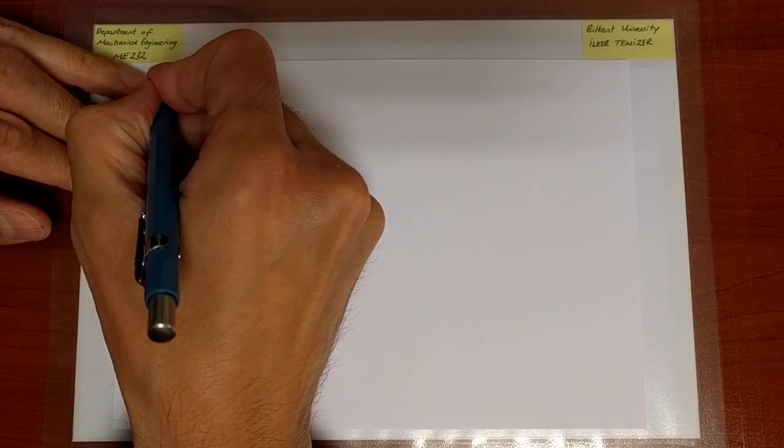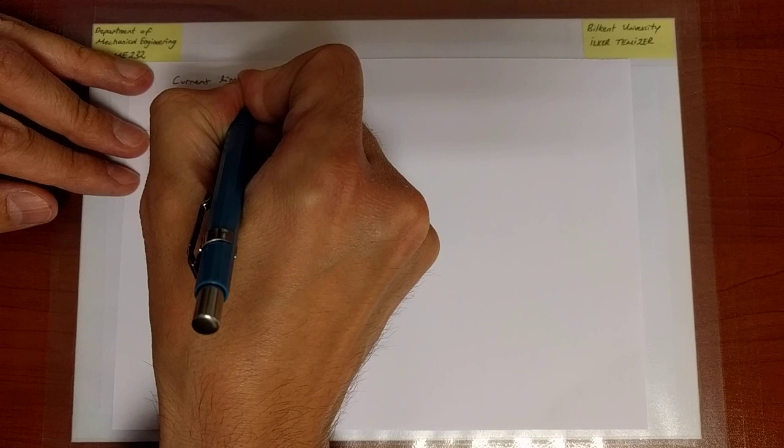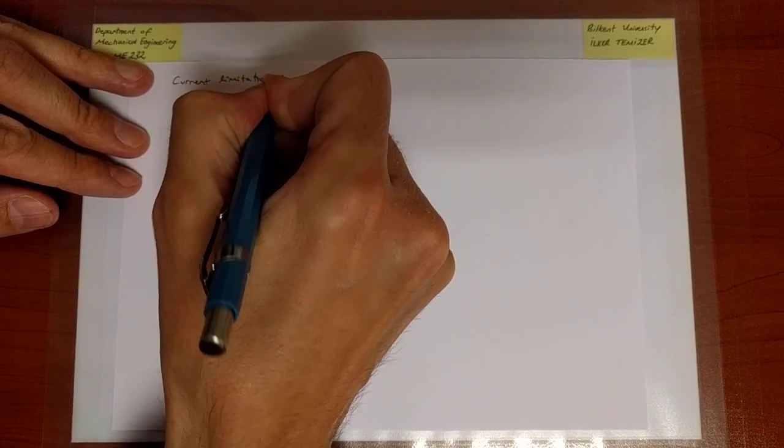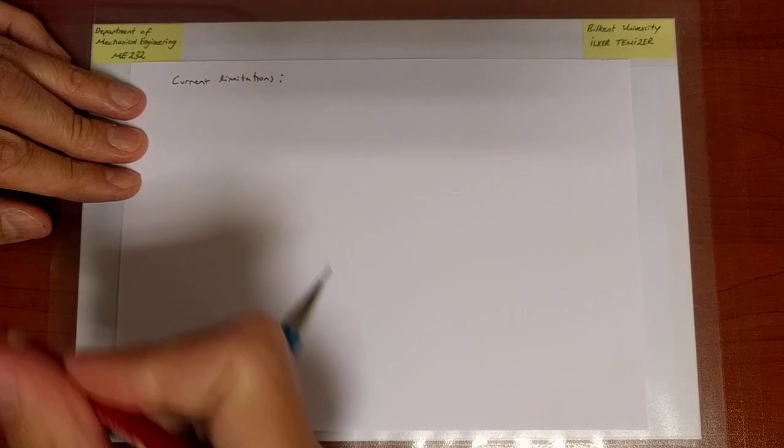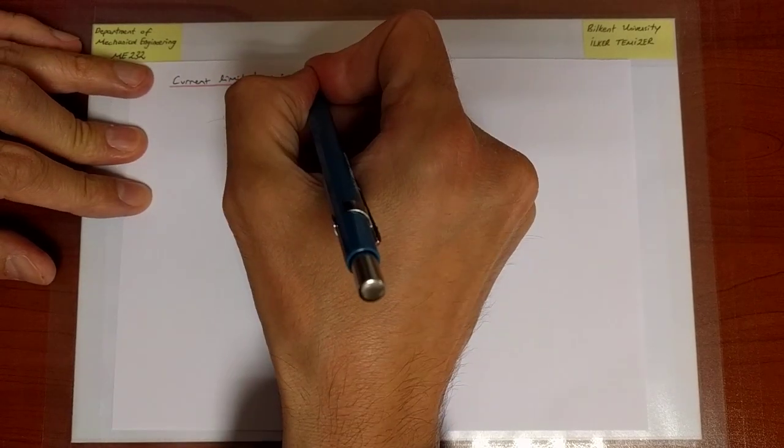Now we're discussing the strain-based approach to fatigue, and we've already established a relation, the Coffin-Manson relation, that essentially delivers us the number of cycles to failure given the total strain amplitude. We do, however, immediately recognize that we have certain limitations, and these are important limitations that we previously addressed in the context of the stress-based approach to fatigue. Let us summarize once again and highlight their importance.